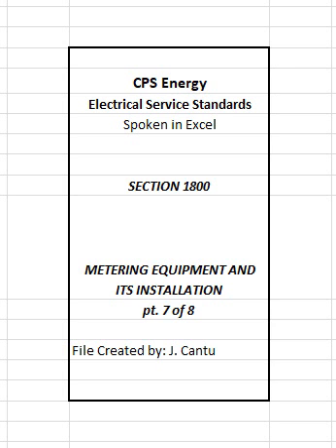On existing commercial buildings where auxiliary wire gutters are used to group meters, and the wire bus or gutter needs to be enlarged for more load or meters, an auxiliary bus gutter must be used if the supply conductors or any one set of service entrance conductors in the gutter exceed 1 to 500 kcmil or 2 to 350 kcmil conductors per phase.